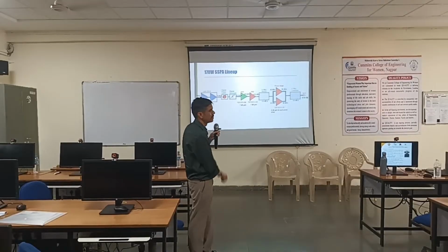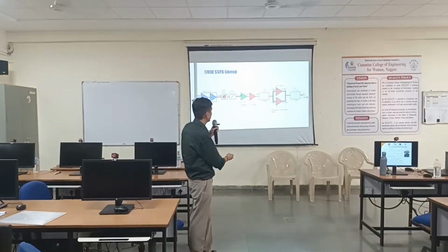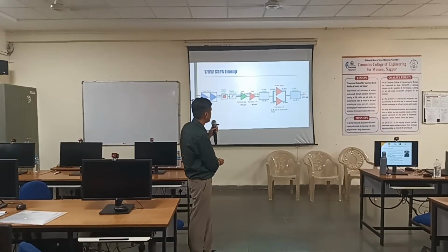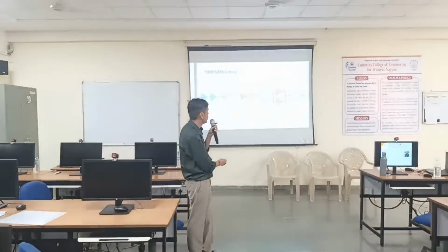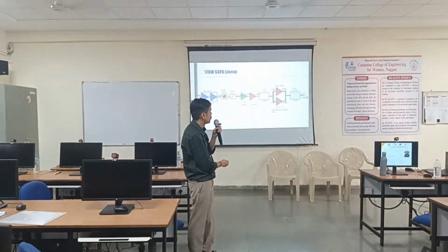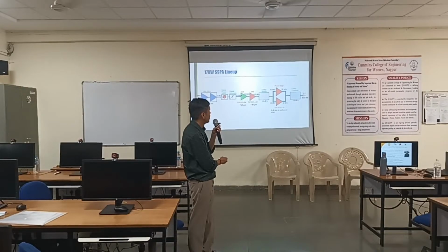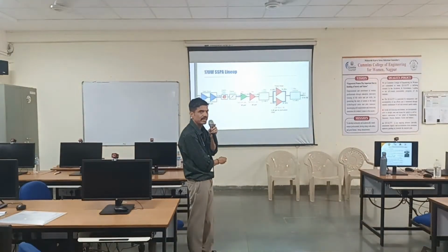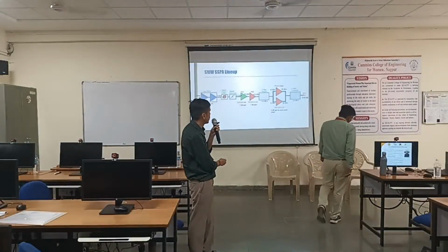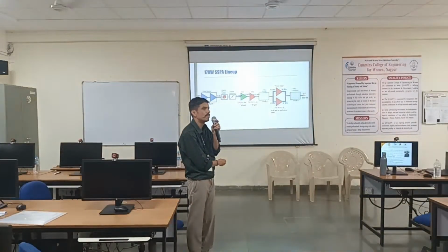This setup you can see. Now if I have to calculate the efficiency of this stage, you see the gain here: 8 dB, 7 dB, 7. If I have to see the efficiency for, let us say, this stage, how do I calculate? I calculate the output AC power divided by input DC power, right? That is my DC efficiency. But where is this power you are considering? You are not considering it. 42 dBm means how much watts?